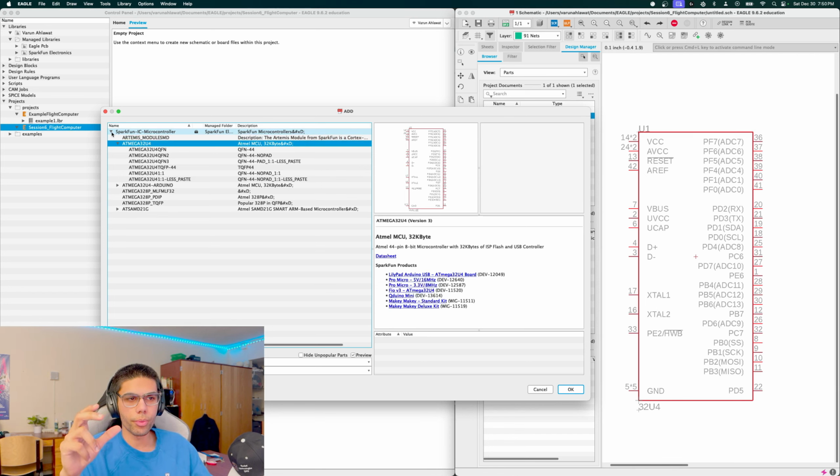That accelerometer could tell us a lot. Imagine that a rocket is standing on our launch pad. So the acceleration is 0 right now. Imagine now there's some value of acceleration along the x, y, and z axis. You can integrate that acceleration over time to get the velocity, and then integrate that velocity over time to get the displacement.